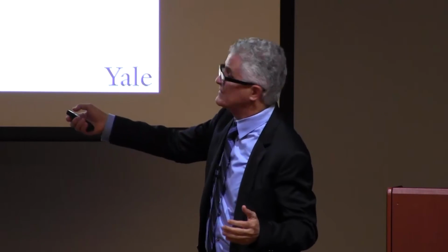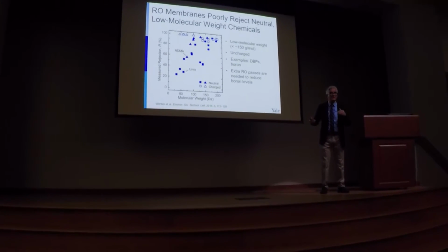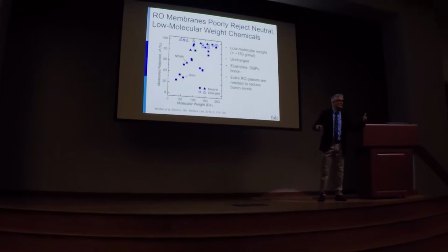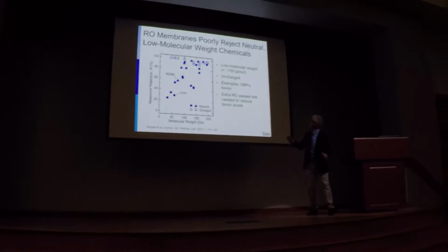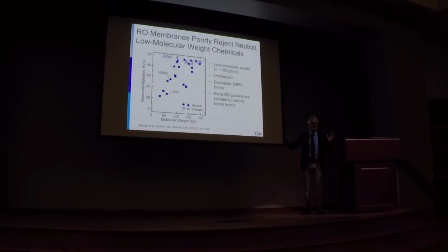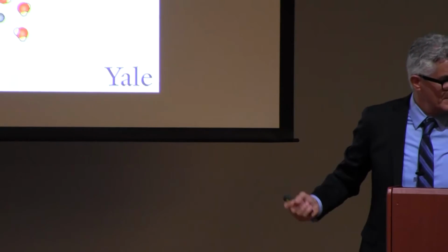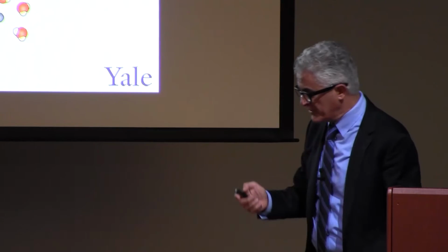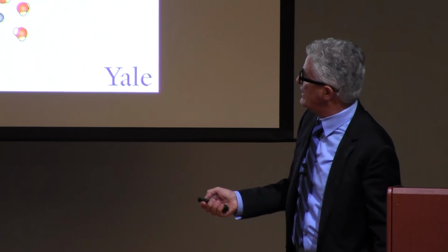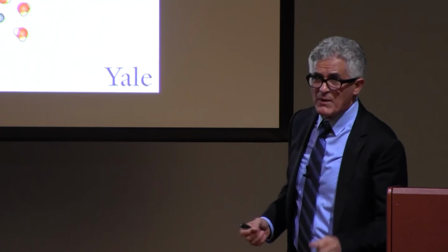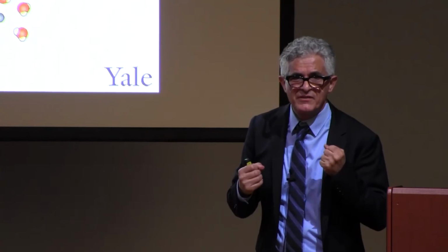This can be a major problem in wastewater reuse, because when you recycle wastewater, the last stage is reverse osmosis, and all of these toxic chemicals, of low molecular weight, can go through, and you need to add another 1 or 2 barriers to prevent them. So if you can really have a membrane that rejects everything, it will be great. And here we discussed this issue in a recent review article that you see here, and we talk about future membranes that can really achieve high selectivity.